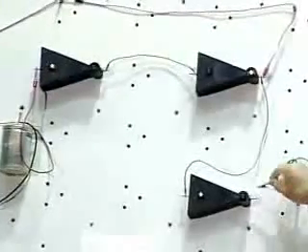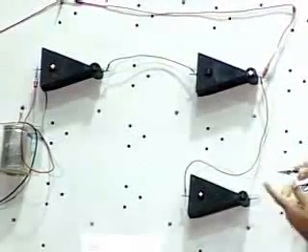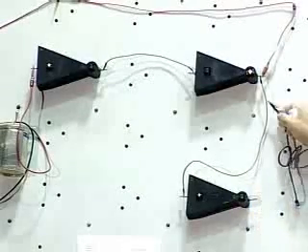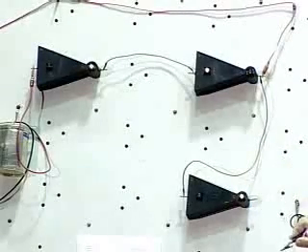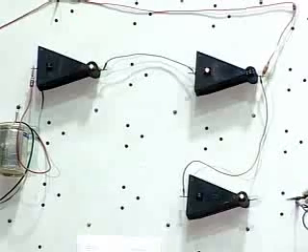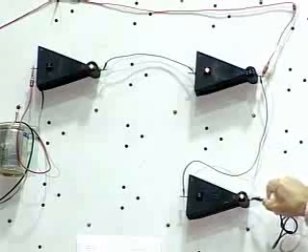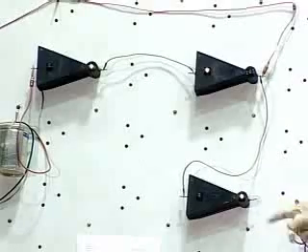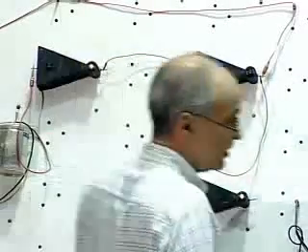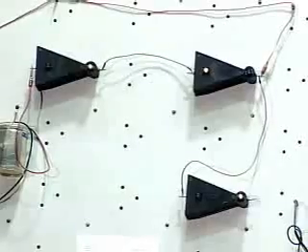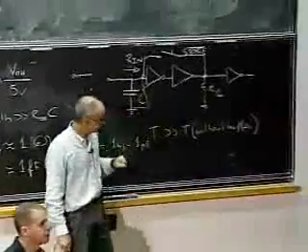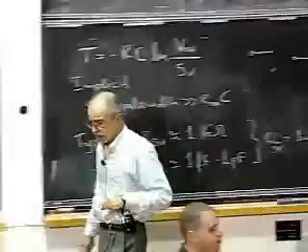I can do anything I want here. Nothing happens, but you may say this is a trivial case because this is already 0. So I'm going to change the state. Here's the state changed. Now, see, I can short this. Nothing happens up there. So this is an interesting situation in which I'm buffering the output so that the output does not feed back to the input. And by and large, in designing circuits, this is something that we do.